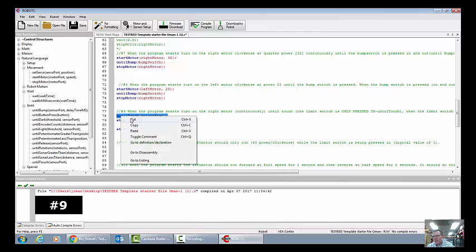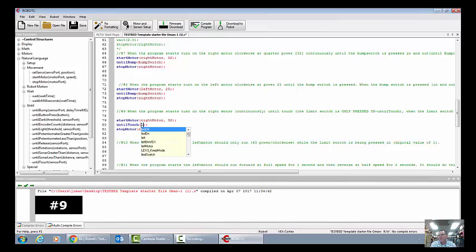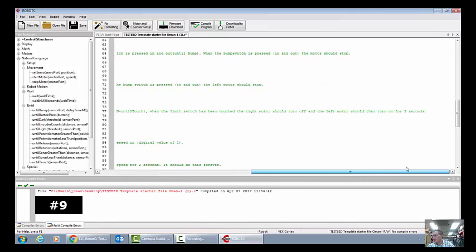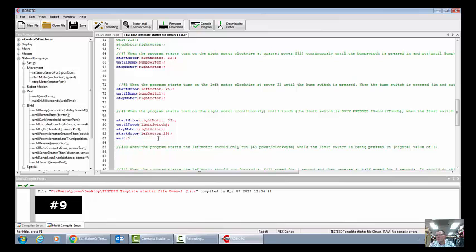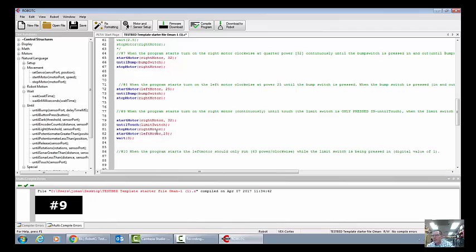I'm going to need to switch these around here. And that's the limit switch. There, and then the other motor should turn on. Left motor. Okay, so the first motor is the right motor. It's being operated with the limit switch, and the second motor, the left motor, we are using a wait time. So I'm showing you here that wait and until commands, you can use either one.